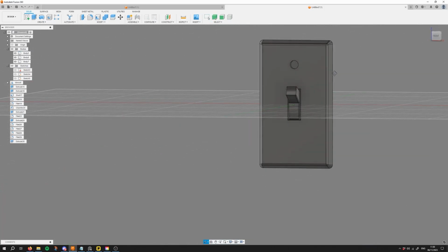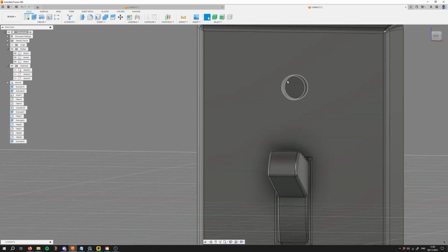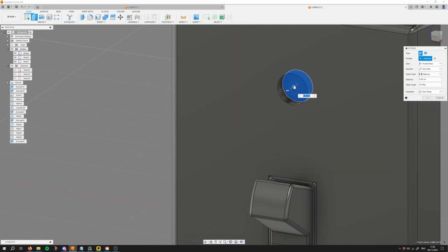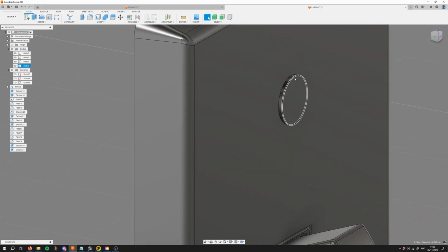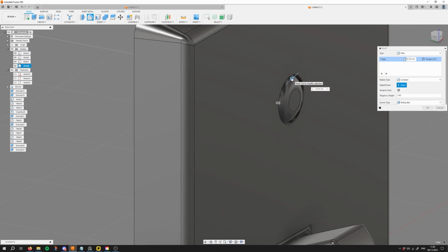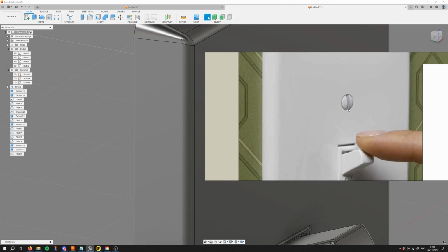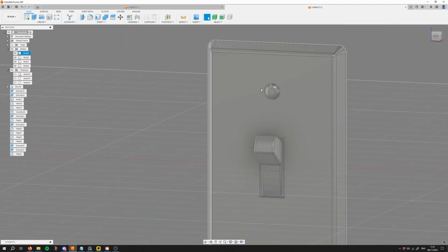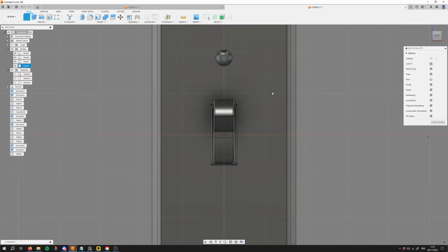From that cut, we can make our first screw. We select this face and extrude it out. Don't press join. We wanted a new body. Press it. Select the outer edge. Press F to fill it. And if we look at the references, we can see it has a little rectangular inset. So let's sketch on this profile. Create a new sketch. Press that face.